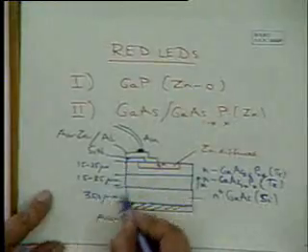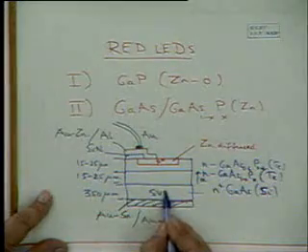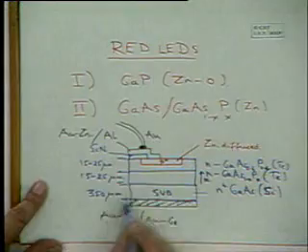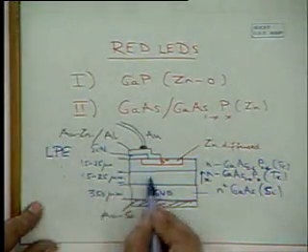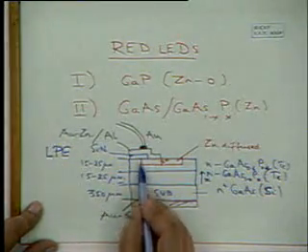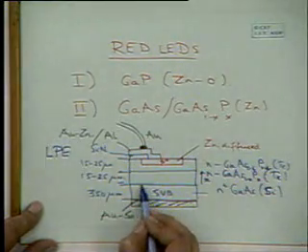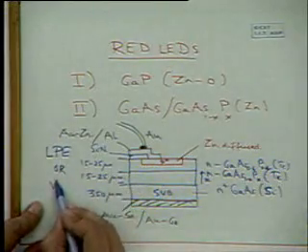What is the third possibility? Oh, incidentally, on the 350 micron substrate, you grow first a graded layer and then a constant composition layer. These layers can be grown by LPE, which is very good because you can grow fast. It's not sub-micron; the total thickness may be something like 30 to 50 microns, so you can't spend a whole day growing the layer. So LPE is very good, or VPE.